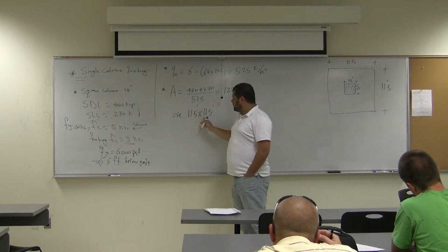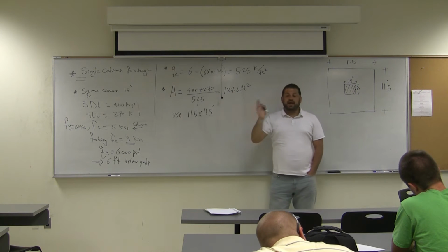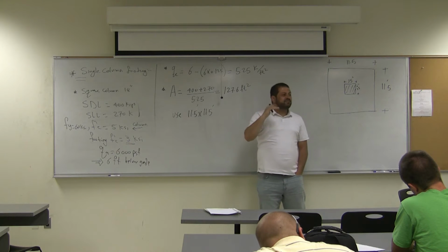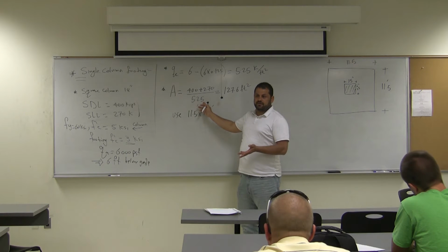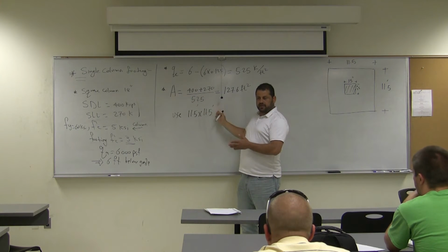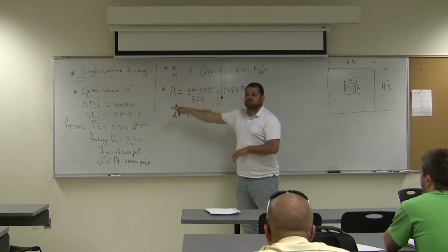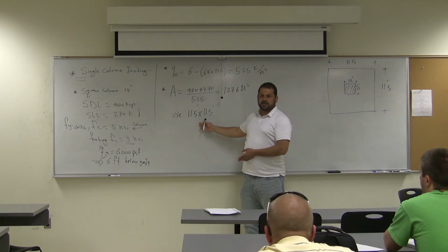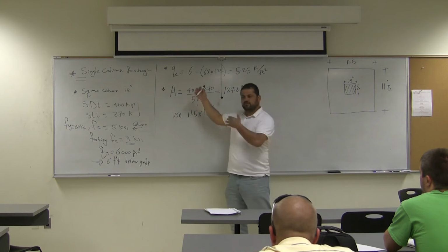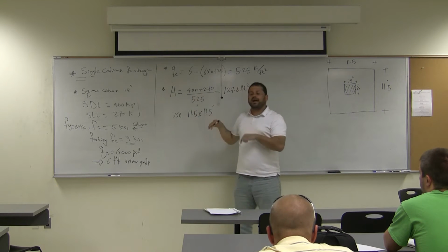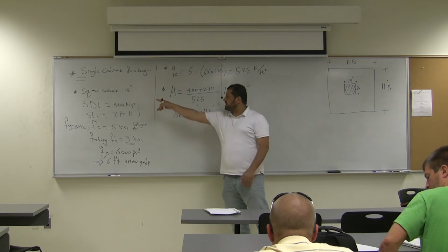Okay, guys. Now, once you have this area established, there's one more Q that needs to be calculated for strength design, and that Q is calculated based on the factored loads. These are common mistakes, guys. Some guys divide by 6 in here. Some may do it right. Now, when they want to calculate Q effective, they will divide the service loads by this area. When you say Q effective, you subtract whatever is on top. Q ultimate now, not Q effective, Q ultimate for strength design must be based on the factored loads.